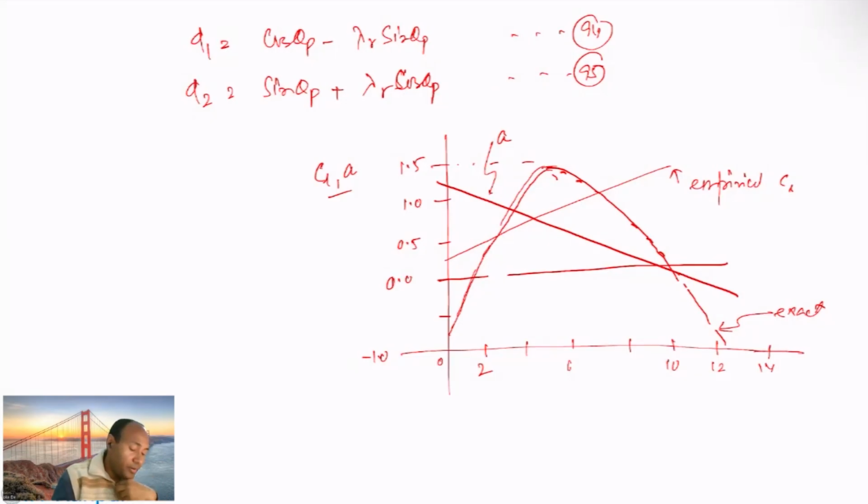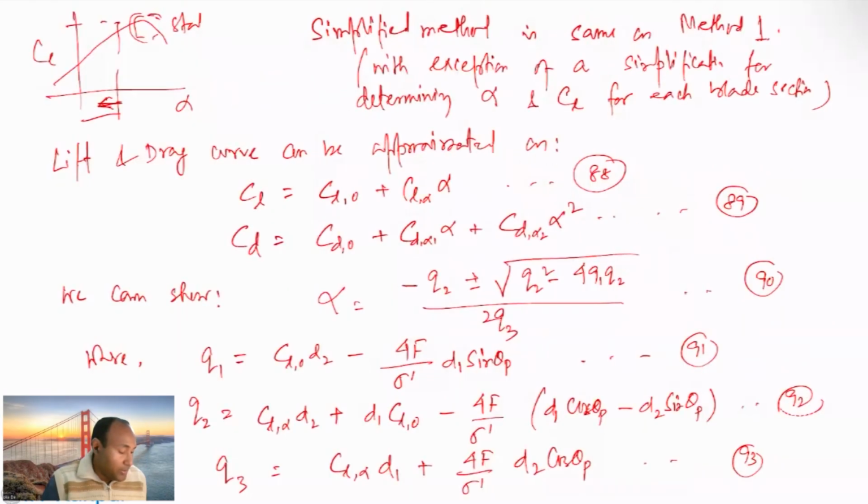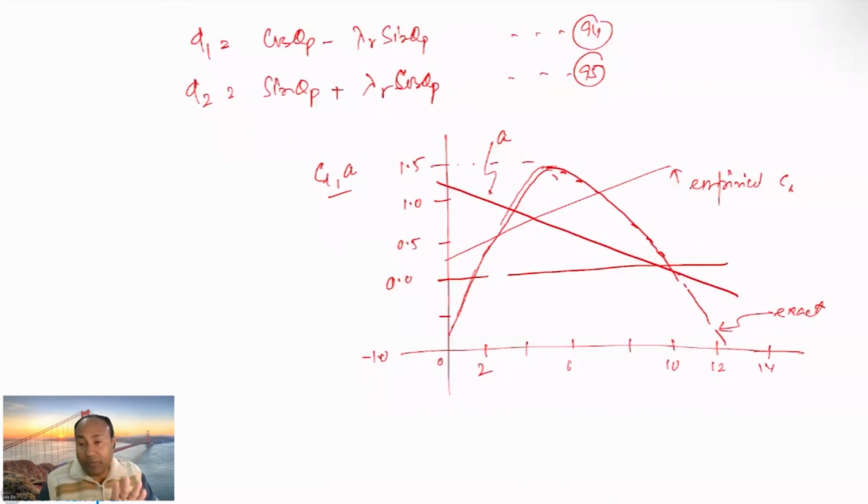Obviously, it depends on the airfoil and the flow conditions. As we have talked about, the applicability of this simplified method is essentially in this particular range where you are away from the stall region. But for certain high angle of attack stall conditions, this can be used also. So this is how the design procedure works, but we will see other parameters' effect in other systems. Thank you.